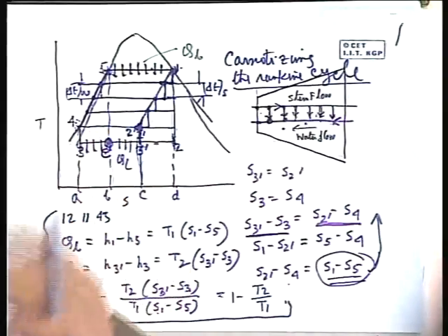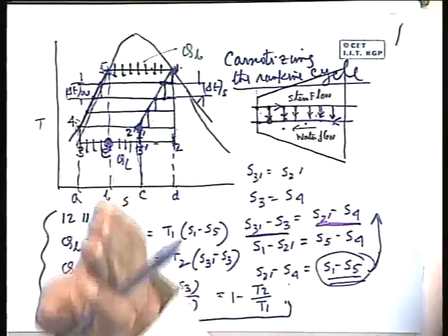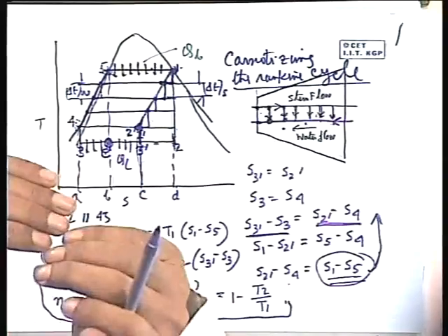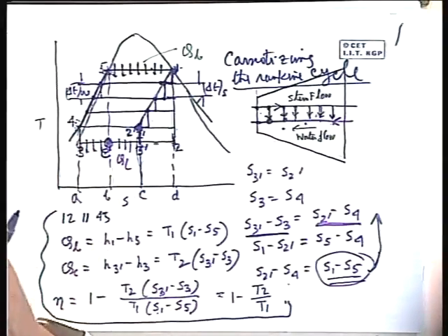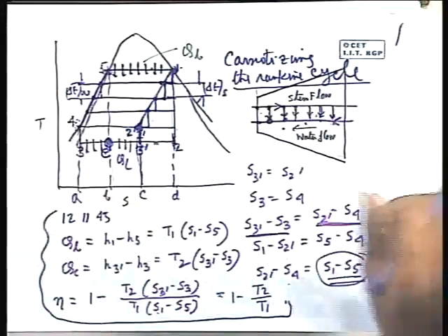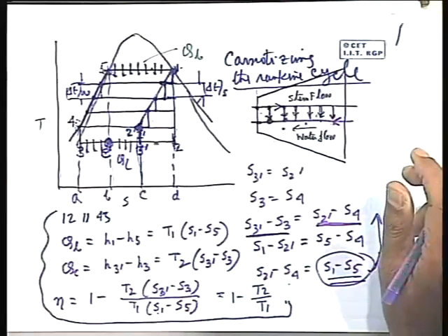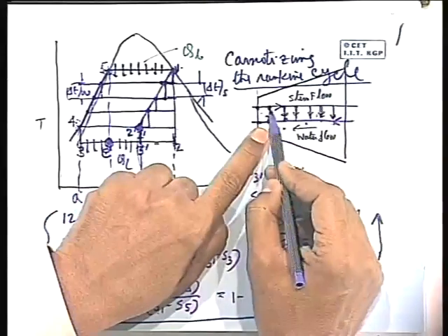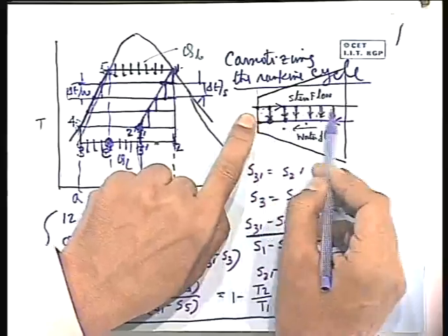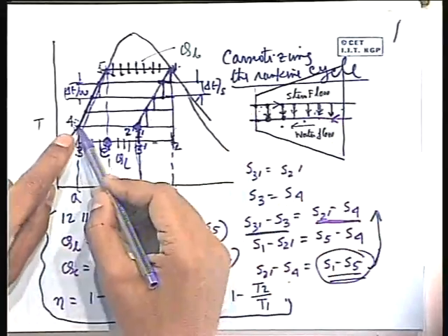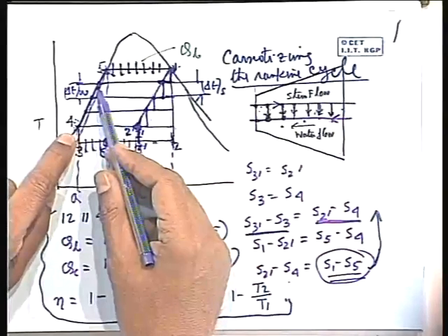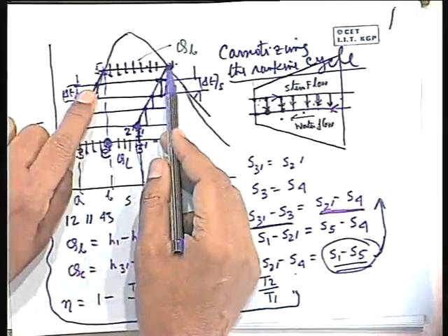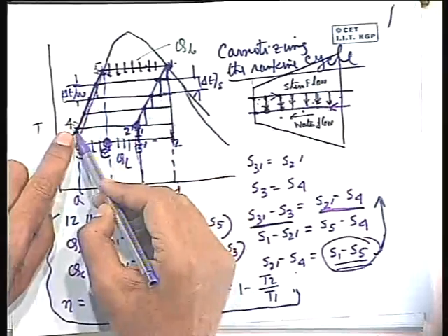Efficiency, if you think in that way, forget about the temperature. The conclusive way of telling whether efficiency is increased or decreased is to think in terms of the temperature ratios. But if you define thermal efficiency from more basic equations, efficiency is the work done divided by the heat added. Now you see, when the steam is transferring this heat in this way, the work done may be a little reduced. Yes. But at the same time you decrease the heat added. You understand? That means the heat added is now H1 minus H5, not H1 minus H4.